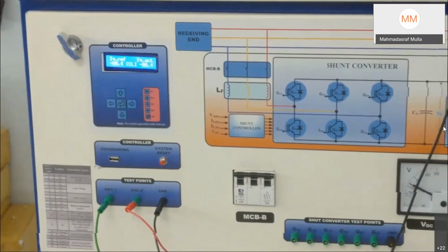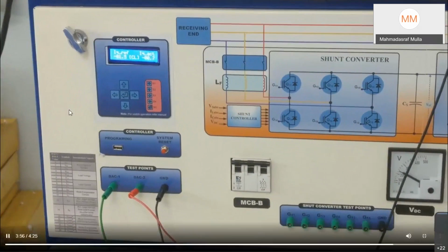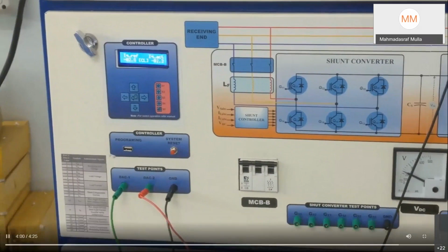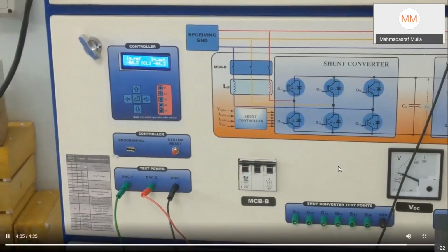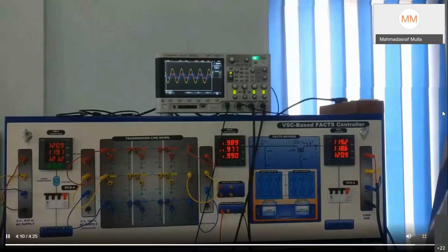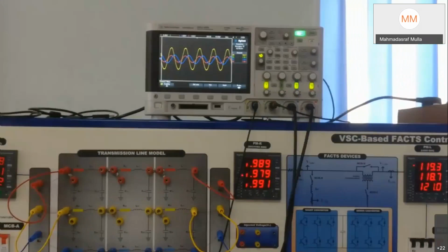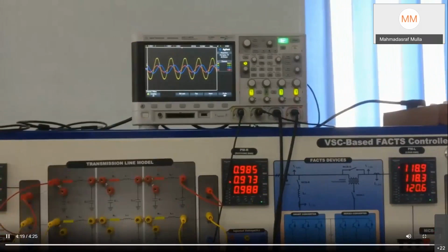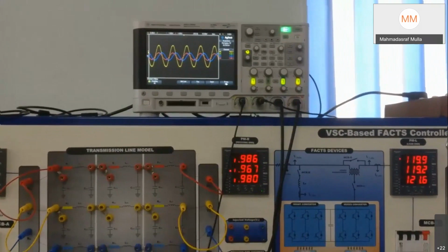As I increase the load in the capacitive bank, compensation will happen and the IQ reference value will increase up to 4.3 at full load. As you can see over here, the scenario now is that my compensation current is lagging because our load current is leading. So by that we are getting in-phase receiving.